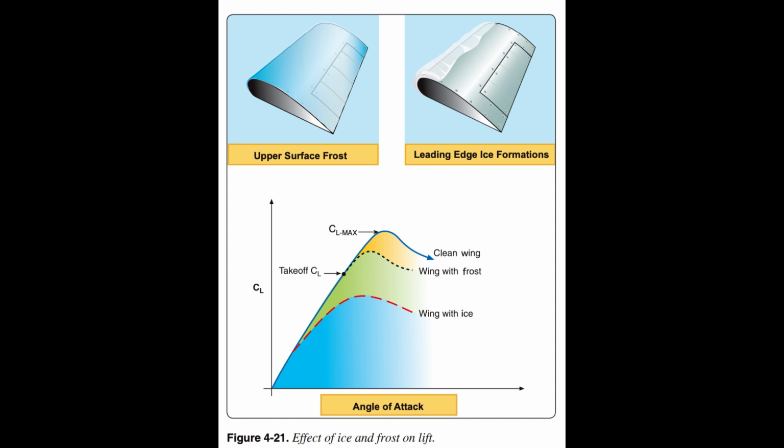Therefore, any accumulation of ice or frost should be removed before attempting flight. Another hazard of structural icing is the possible uncommanded and uncontrolled roll phenomenon, referred to as roll upset, associated with severe in-flight icing. Pilots flying aircraft certificated for flight in known icing conditions should be aware that severe icing is a condition outside of the aircraft's certification icing envelope.